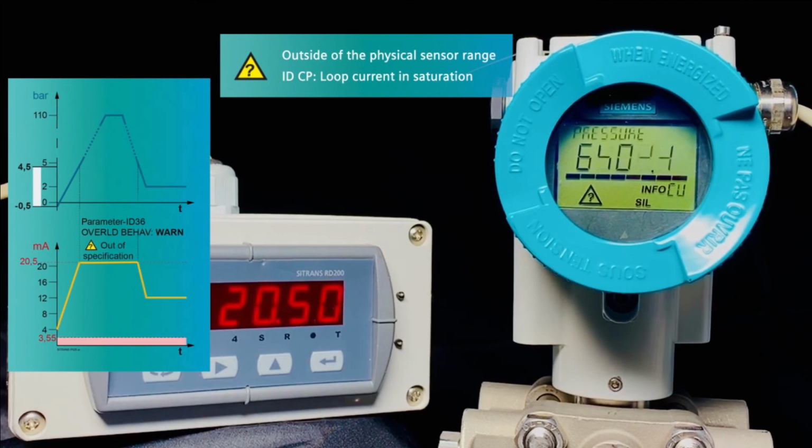When I reduce the pressure and I am within the valid measuring range again, the device measures. This means cascade measurements are possible with the setting warning at parameter 36 overload behavior. Please note that you must take appropriate measures in the warning mode to prevent overload of the measuring cell.